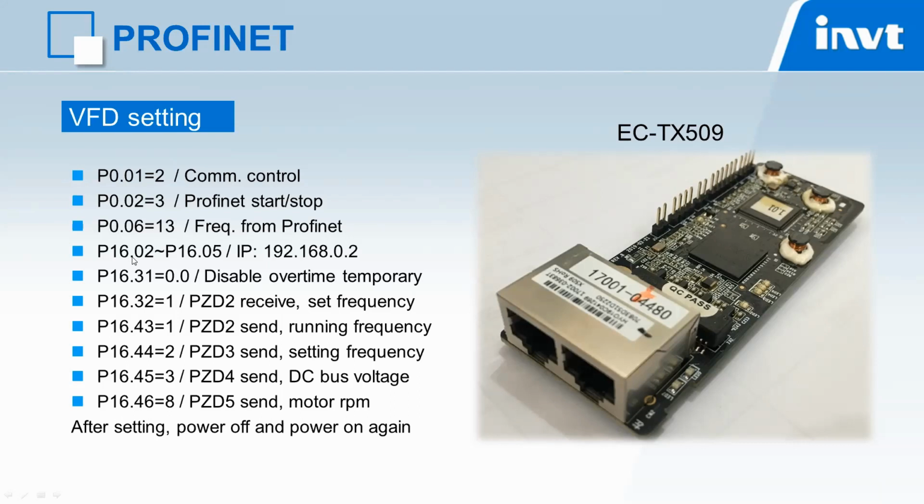The P16 group is for the Profinet settings. From 2 to 5, it's the IP address. The default is 1. We change this to 192.168.0.2. We must make sure our computer IP address and the PLC address have the same first 3 numbers, and the last one must be different.